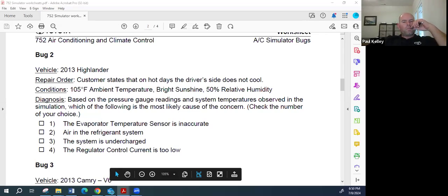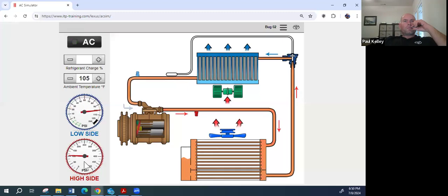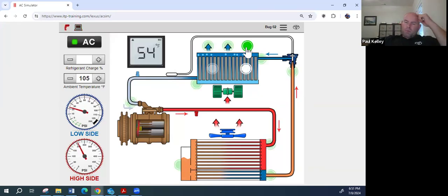Look at it. We were supposed to have like 130 PSI and we had 102, 103. It's undercharged. What's interesting is when something's undercharged, you have a limited quantity of refrigerant going through the system. The refrigerant enters the evaporator and does amazing things. And then by here, it's already kind of evaporated, and by here, all the refrigerant's already evaporated.